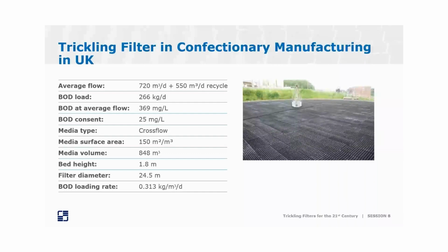It also needed more wetting rate on the media because it's a more open structure than the mineral. So that's where recycle is often incorporated with plastic media to make up the difference if required.